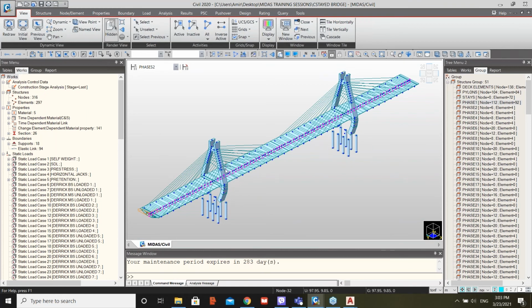Then we post-tension some bars and cables to keep the segment in place, finish the segment on this side, and switch to the other side. That's why they call it balanced cantilever: you erect one segment at one side, then go to the other side and erect the other segment, and that's how the construction progresses.